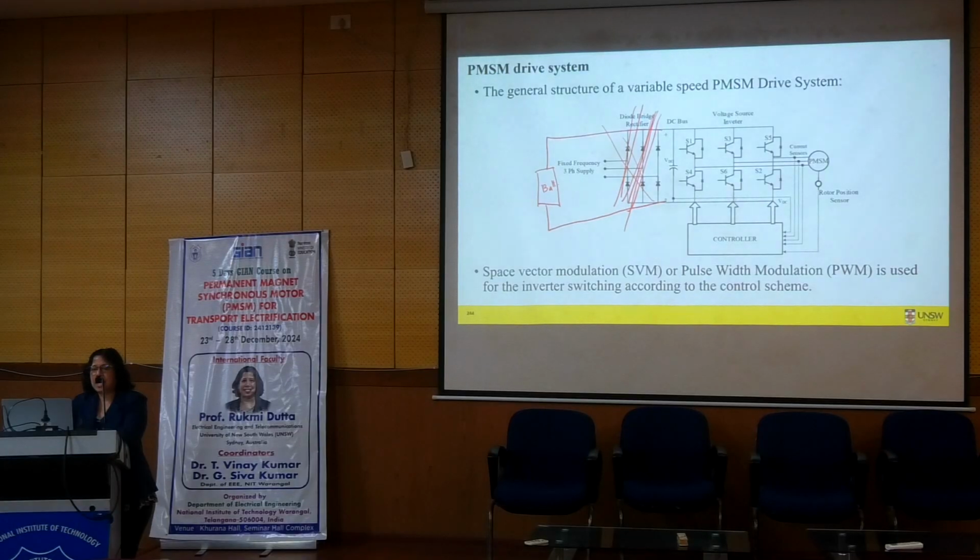You may or may not have that DC-DC converter in between. And then we have this 2-level 6-switch conventional 3-phase inverter. The controllers that we are talking about, whether it is V by F, I by F, or FOC, are here, this controller, which is in a microprocessor.